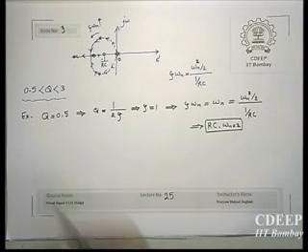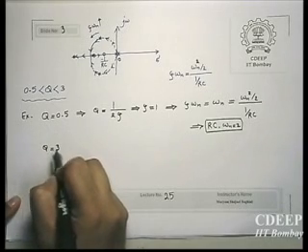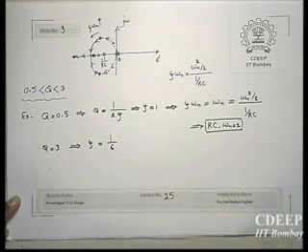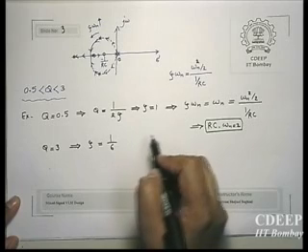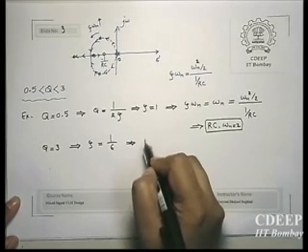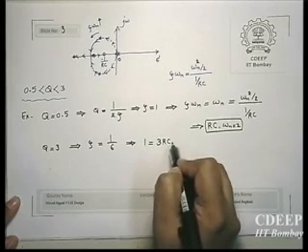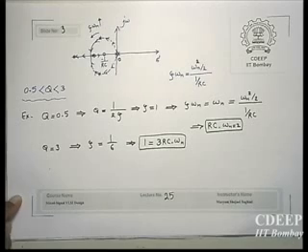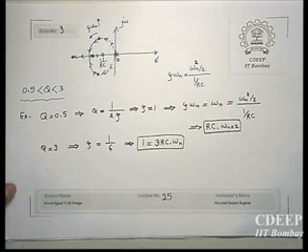Now if you choose, for example, Q equal to 3, then that means your zeta is equal to 1 upon 6. If you remember the last-to-last example, zeta was 1 upon 20, which is too small. So zeta is equal to 1 upon 6, and therefore you will get this new relation: 3RC into omega n. So now your omega n is 1/3 of omega 0, so omega n shifts to the left, and your crossover frequency will be well above the resonance frequency of the loop.